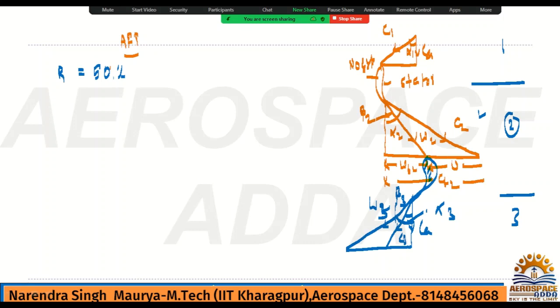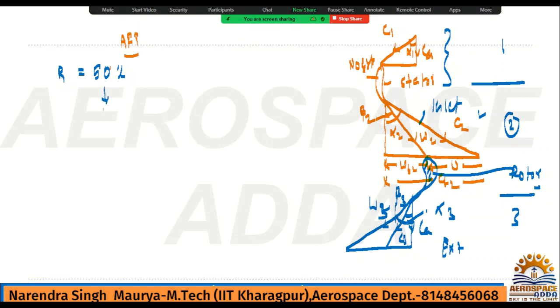Alright, now check, they have mentioned R, 50% degree of reaction they have given to us. So for the rotor 50% degree of reaction they have given to us. So you just forget about this, this is not for our use. Okay, this is the inlet triangle, and this is the exit triangle, and this is the rotor. So across rotor what is the inlet and exit we have to check. So it is 2 and 3. So for 50% degree of reaction I explained you it is 2 and 3. So that means alpha 2 will be beta 3 and beta 2 will be alpha 3. That's the meaning of it.